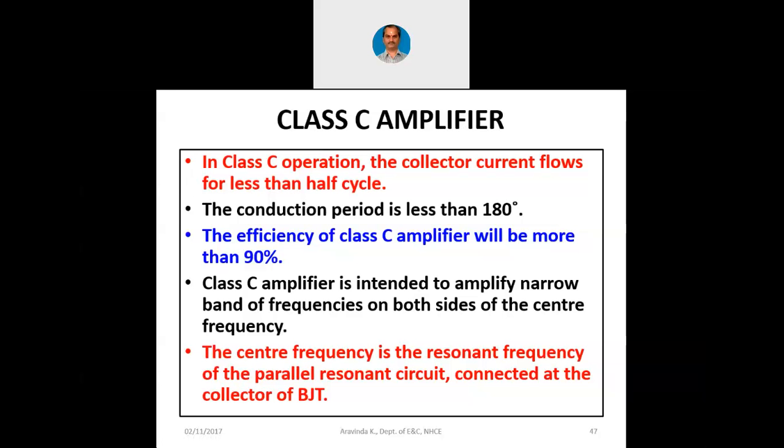2.4 gigahertz. Whereas for an audio amplifier, we will have to use the amplifier right from 20 hertz to 20 kilohertz. So the bandwidth is 20 kilohertz in the case of an audio amplifier. In the case of a radio amplifier, when this is 2.4 gigahertz, the bandwidth can be much lesser, maybe a few kilohertz. Even though we are using a frequency of gigahertz, the bandwidth there can be only a few kilohertz. I am going to show you those waveforms or pictures later on.